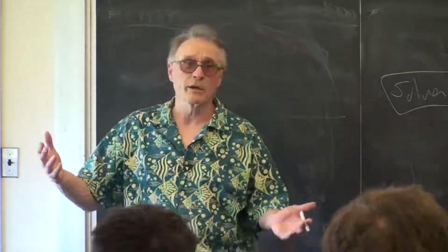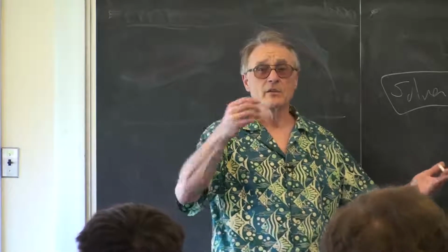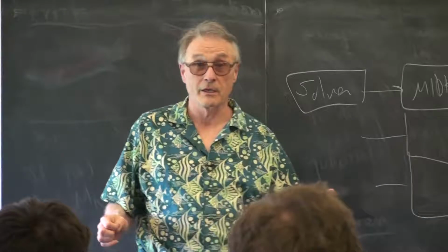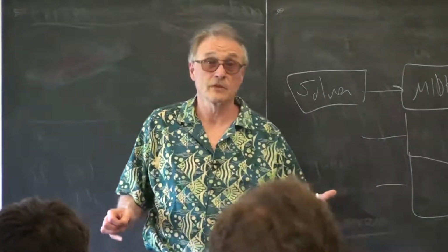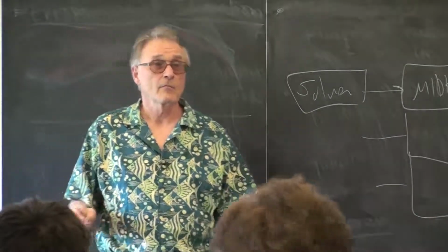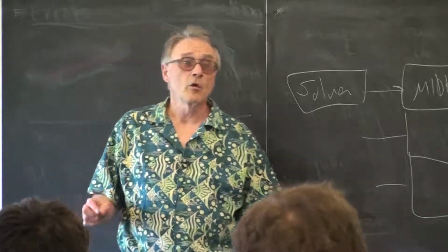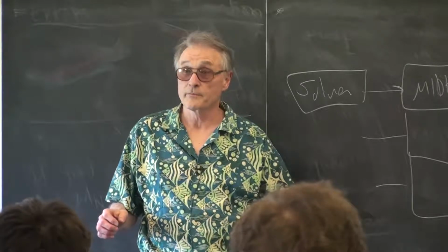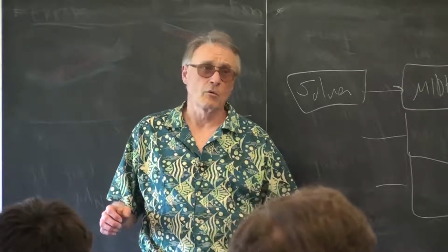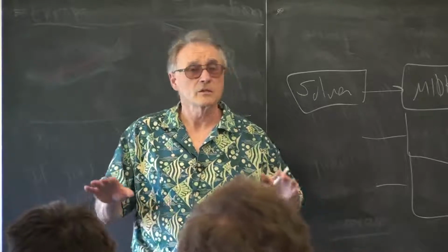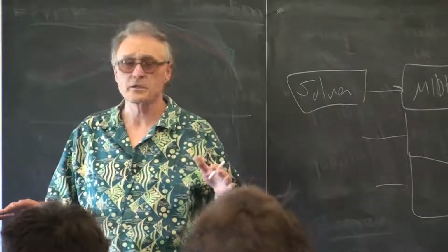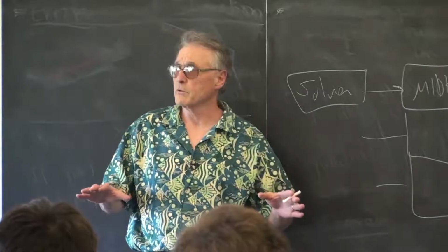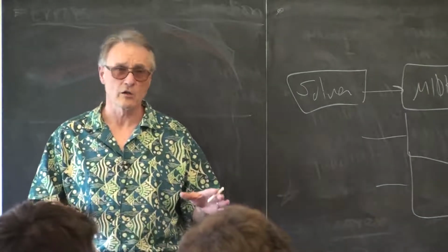For instance, let's say you wanted communication from the PC to the FPGA fabric. It would make a lot of sense to use HPS to do the Ethernet, because otherwise you'll cry. It's really hard to do Ethernet by hand. Although I have seen people roll their own UDP stack in hardware. But you don't want to. So I would guess that many of the projects are going to be using some combination, and that's really what I would prefer, but I'm not going to enforce that. If you want to do all FPGA hardware only, that's okay.